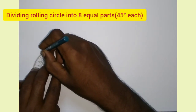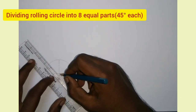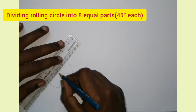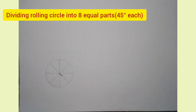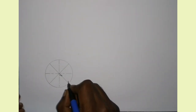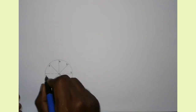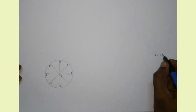Now I am going to divide the rolling circle into 8 equal parts, that is 45 degrees each. Okay, I am marking points as 1, 2, 3, 4, 5, 6, 7 and 8. And the radius is 25 mm.